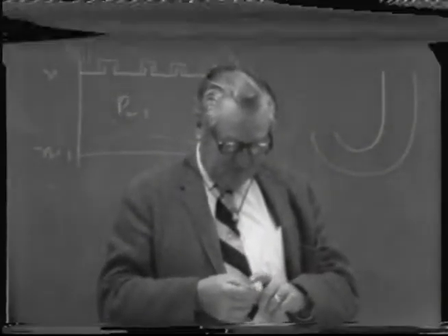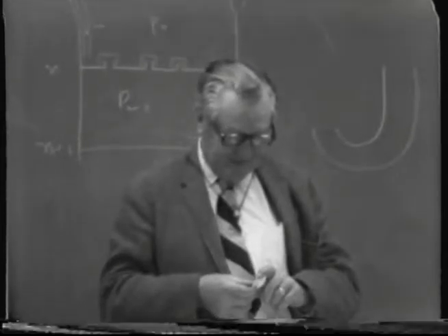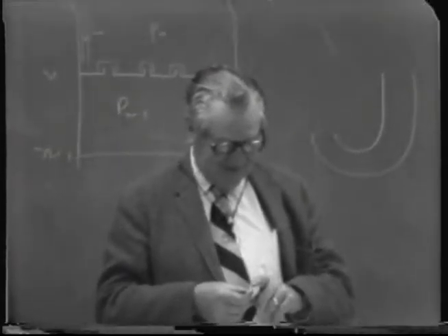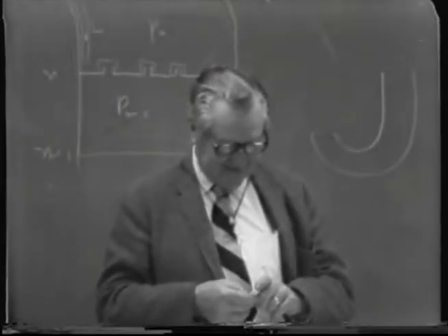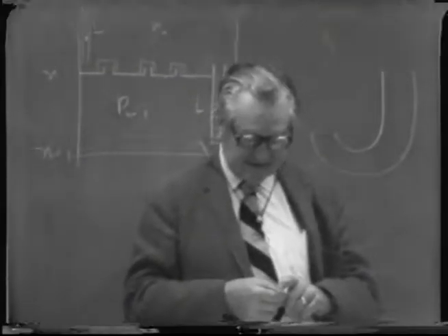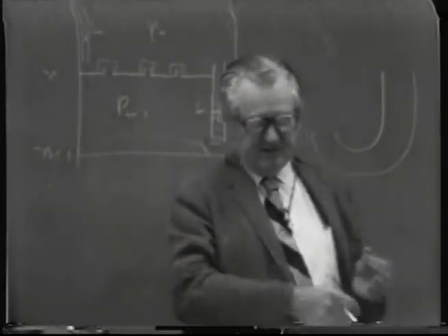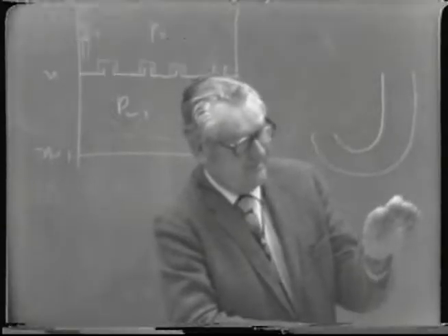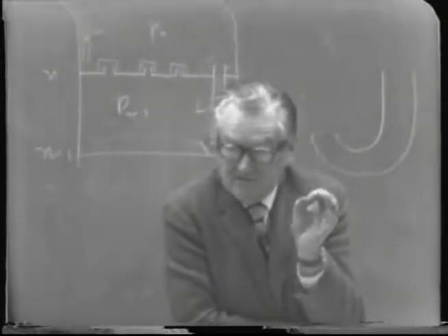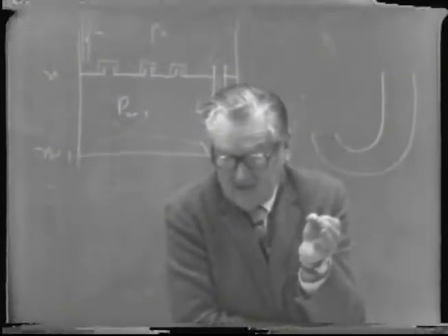But I visited one place where they were having a terrible problem with loss. Couldn't get any efficiency in the stripping section. And so I looked in it, and they had drilled out the holes till they were, I think, either 3/4 inch in diameter or nearly 1 inch in diameter.